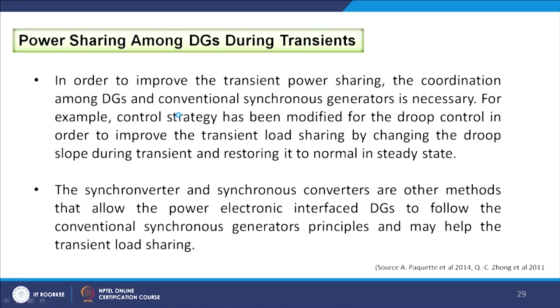Now, the second important part is, when we would like to connect your islanded AC/DC smart grid to the grid, how do we do it? The best practice would be that you keep observing the voltage of the grid, and once it is close to my grid voltage, then I can jump into grid connected mode from islanded mode.